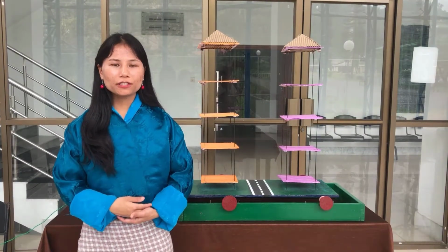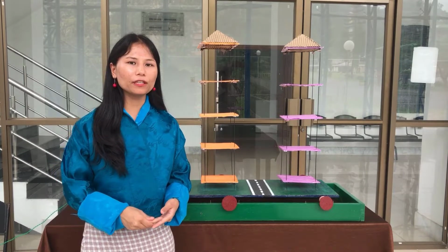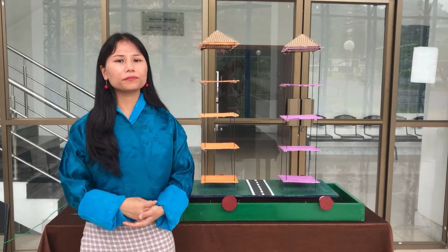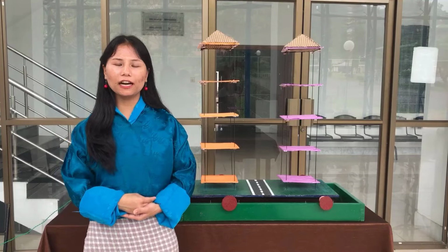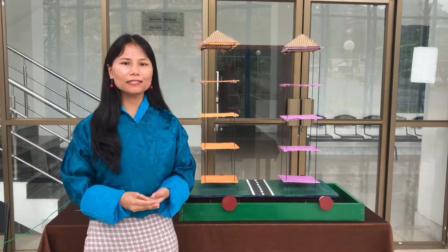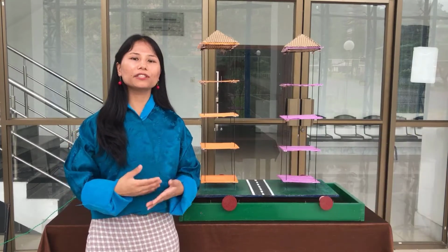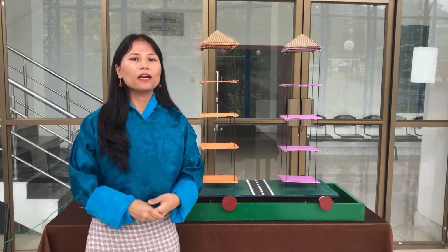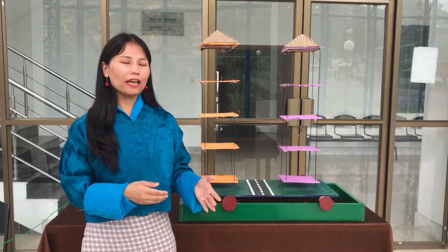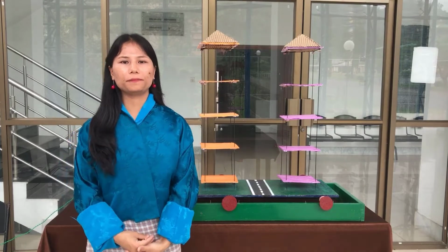To counteract these forces due to seismic events, we can design the building by increasing the dimension of the vertical components such as columns and walls, which stiffens the structure. Well, this is the last option taken by the architect. So engineers have to sit back and look into some unconventional techniques, one of which is to tune a building like a guitar. Yes, you can tune a building just like your favorite instrument. However, you must be wondering how it is done, right? We have the solution, and that is tuned mass damper, which is also known as harmonic absorber.